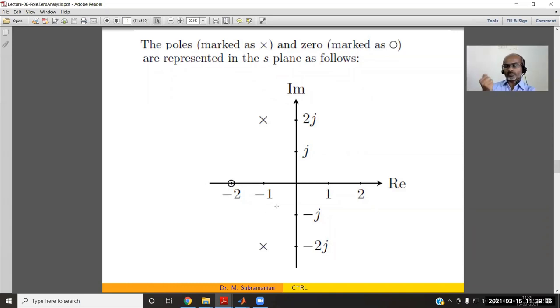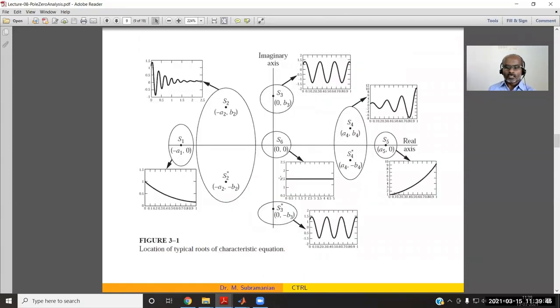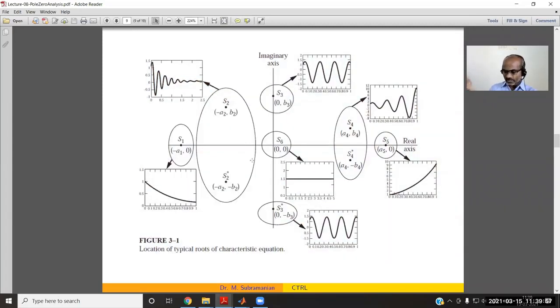So for a second order system with underdamped characteristic, we have a complex number as the roots. And again we are going back. Because of the complex number coming in, we will be getting oscillations in the response. If you take the complex number to the time domain, it will come in terms of sine and cos. The nature of the sine function gives you oscillations in the response.